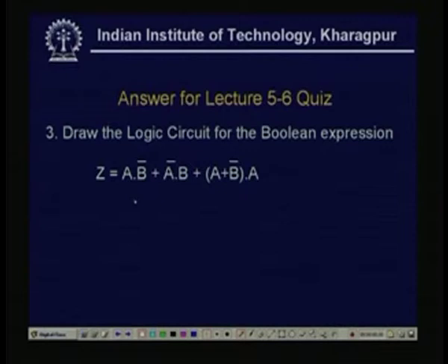See, first, again there are 2 inputs A and B. So, this is my A, a 2 input AND gate. Okay. Now, this is B bar, means B is complemented. So, one inverter, I put a NOT gate, this is my B. So, this is the A B bar.